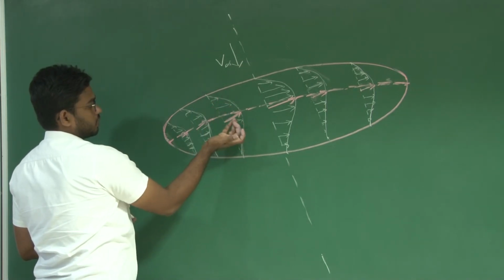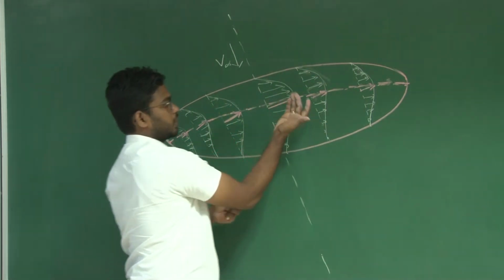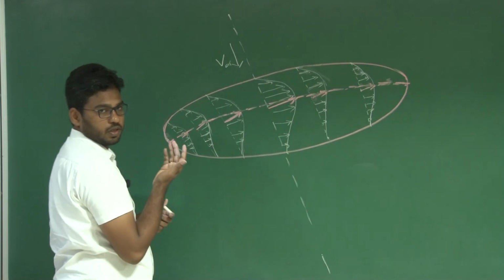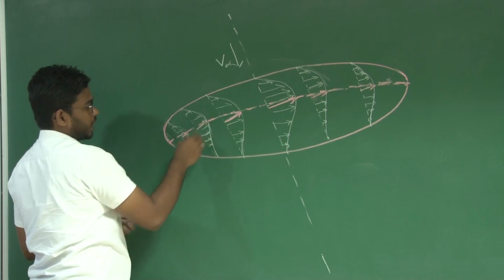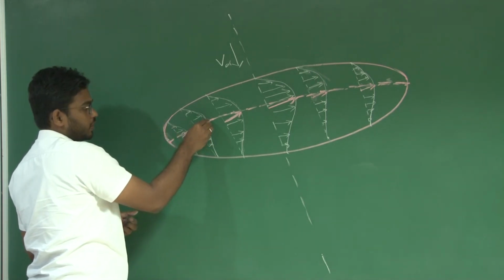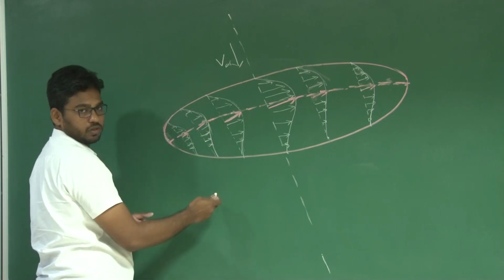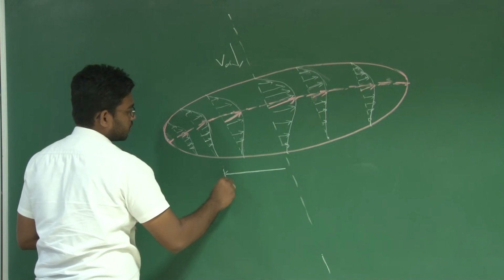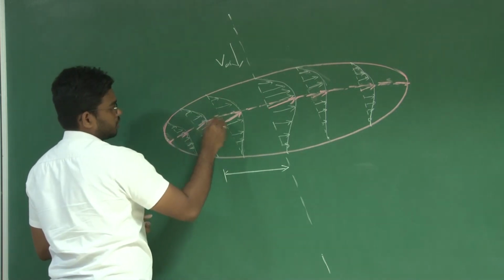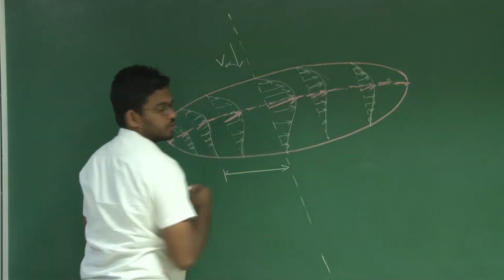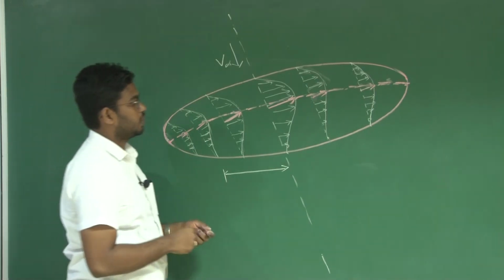Now this pressure distribution is perpendicular to this planform, coming out of the surface of this blackboard. Assume that it is perpendicular to this, and now we can get a resultant force, and a component of that perpendicular to the free stream is the lift at that particular span location, right? Now, if you get the locus of this lift at each and every span-wise location, then typically this is how it looks.